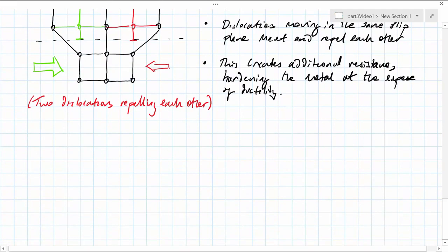For the purpose of this course, plastic behavior can be idealized by neglecting strain hardening. As a consequence, we start with an elastic distribution of stress for a given cross-section.